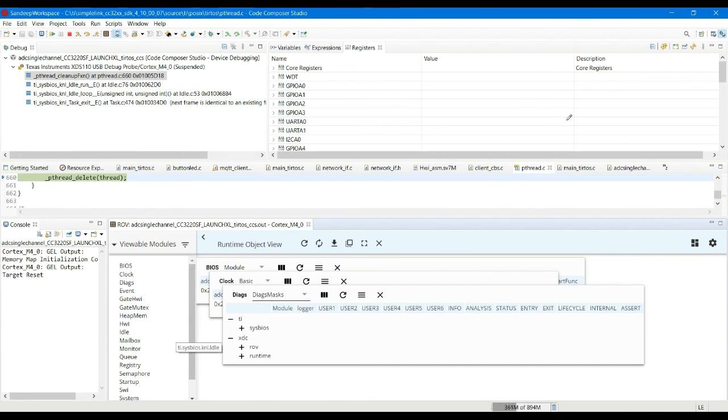In the configuration file, you can also enable logging. If we enable logging, in one of the examples we will do that, then we can actually see in a time graph how threads have been switched. For example, suppose you had two threads of priority 1 and priority 2. One thread was taken up, it finished, and then thread 2 was taken up, and then maybe thread 2 locked a mutex or a semaphore, and when thread 1 was given the chance to run, it had to wait because thread 2 locked a semaphore.